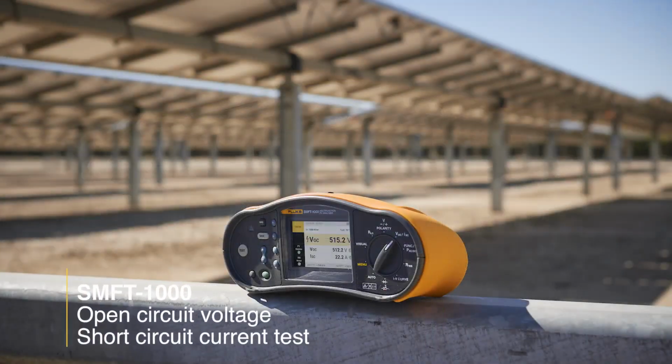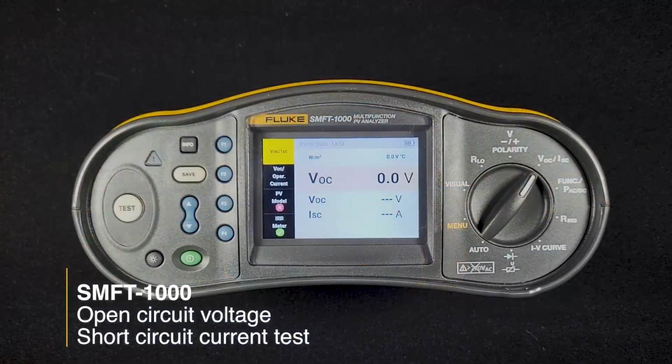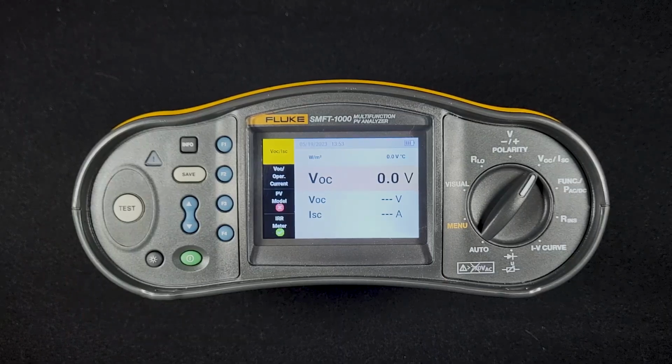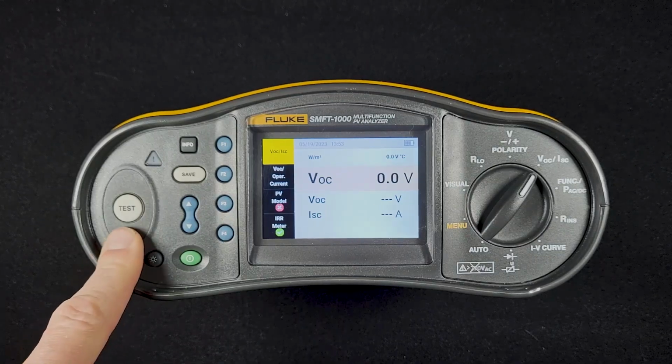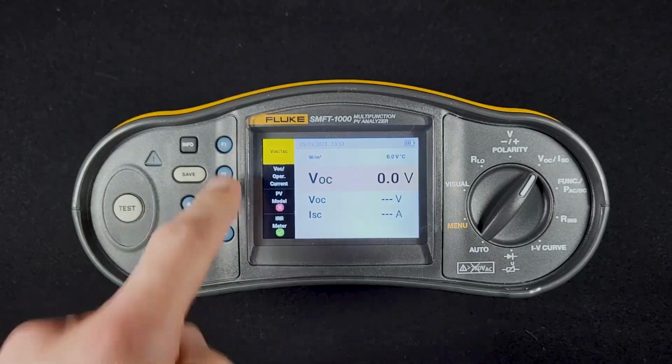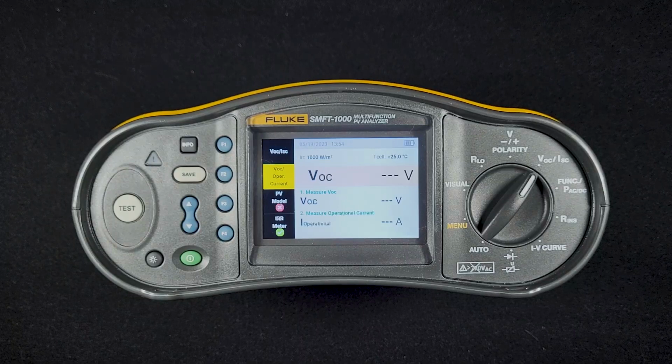We're going to look at the open circuit voltage short circuit current test of the SMFT-1000. Here we can see the screen that we get when we switch to the VOC-ISC test. If this were hooked up to a module or a string of modules, we'd be seeing the open circuit voltage here. If we had the short circuit current, we could run that as well. We would need to hit the test button to see the short circuit current. We can also test operating current and operating voltage.